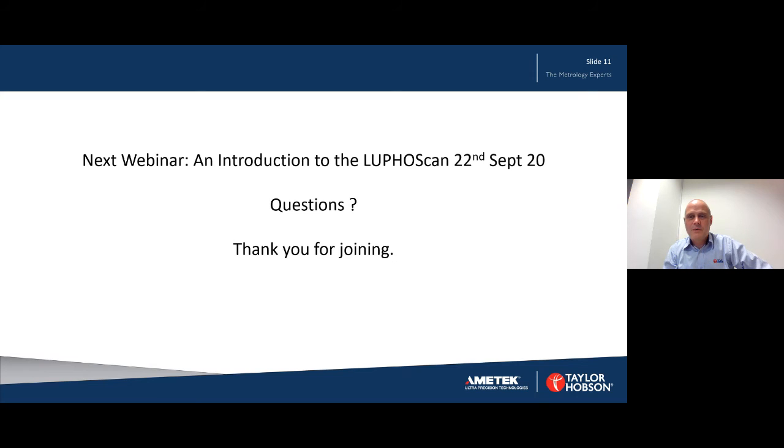Okay, so one of the first questions: is there a good rule of thumb for the number of traces versus which Zernike polynomial orders can be analysed? That's a very good question. If you're looking for astigmatism, a low order form error or maybe coma, then in my experience three profiles would show you what's there. Four profiles will give you a more accurate representation.